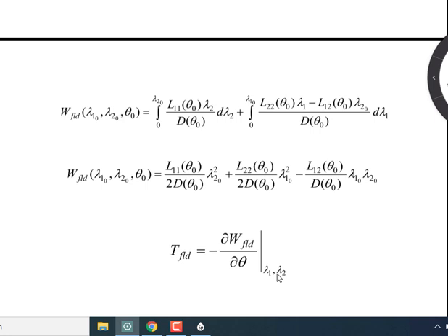Because the source of energy, the mechanism of carrying energy into your magnetic reservoir, is the two currents flowing from the armature voltage source connected across the armature and the other voltage source connected across the field winding. Basically, the separately excited DC machine absorbs energy from them and stores it in the magnetic reservoir, and some part of it is converted into mechanical energy and transmitted to you by the motor shaft. So that is the case here.